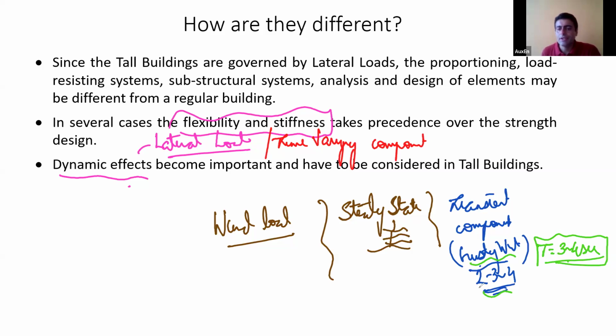I'm saying this gusting wind may have a duration of, let's say, 2, 3, 4 seconds. And if my building fundamental time period of vibration is also in the similar bracket, then this may cause, yes, what Mr. Mehul and Mr. Jay are saying, it may cause resonance. And due to this resonance, there will be an increased response, or what we can call amplification of response.